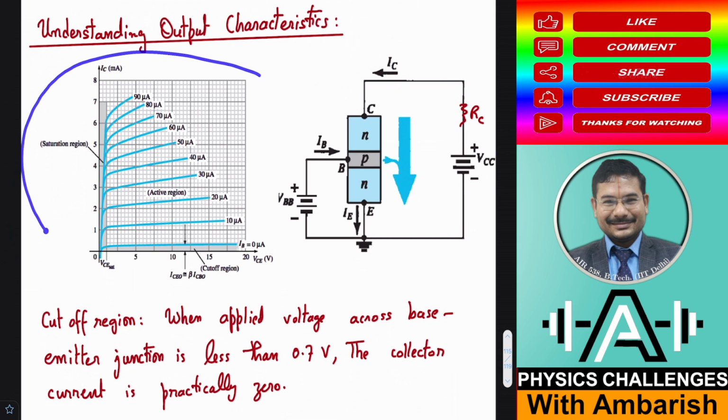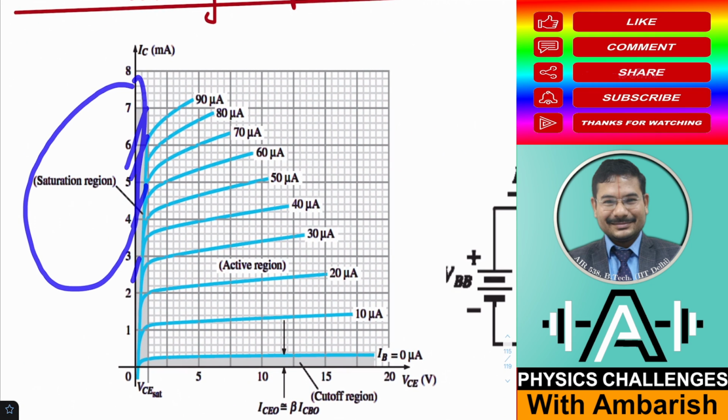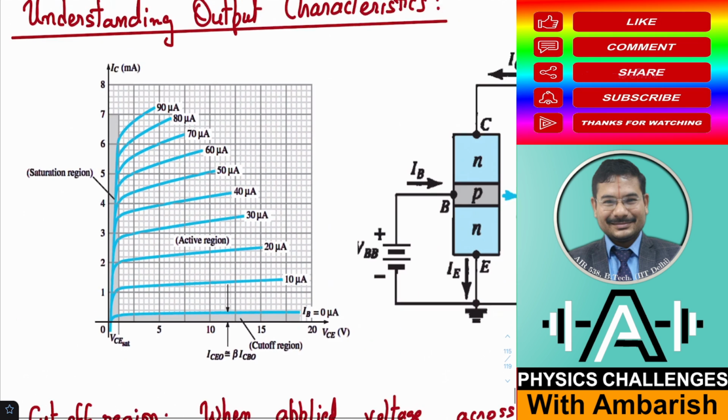And if you see the output characteristics, you can see different regions. In here you can see this is being called the saturation region and this is being called the cutoff region. It's very important to understand what is saturation and what is cutoff. And of course this is where the area of interest is. Mostly we are operating the transistor in the active region. So let's try to understand all these terms. What is the cutoff region, what is the saturation region, and what is the active region.